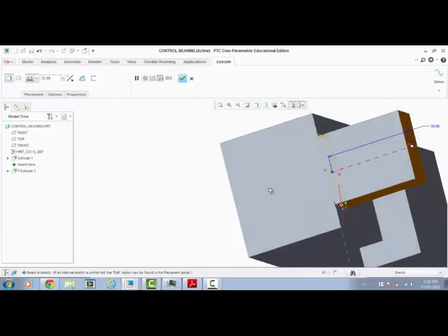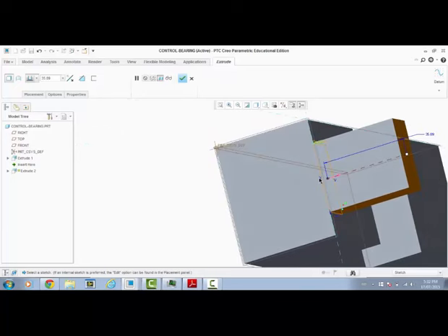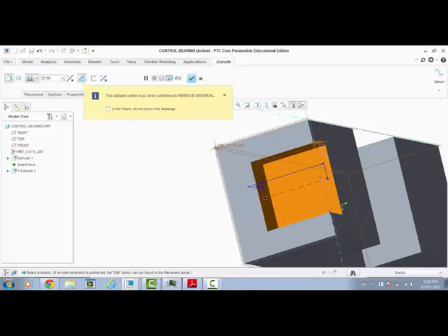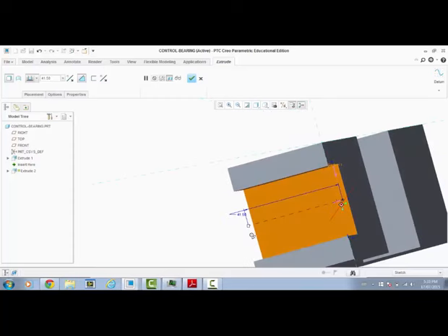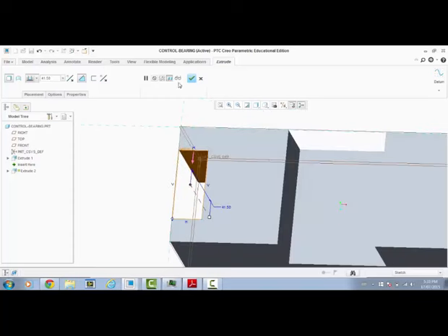It likes that. Now the object is being extruded, but it's going in the wrong direction and it's solid. So we're going to pull it down through, and now it's subtracting this extrusion from it, and we can type in here 41.5, or we could have just done it at this place as well. We press enter, and now it has subtracted this extrusion from our object.